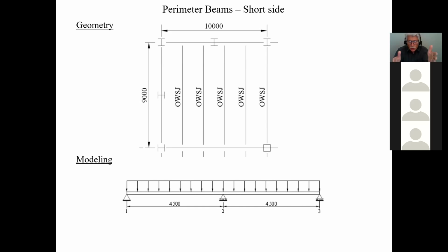Okay. And I can show you how to do that on ADA. Very simple. That's where you have all those other load cases, like P1 with a factor of 1, P2 with a factor of 1, and those are the ones you look at. Understand? Don't look at the envelope, because the envelope is going to show you each deflection of each case, but you won't be able to see the values from the envelope. You're going to have to do each one individually.